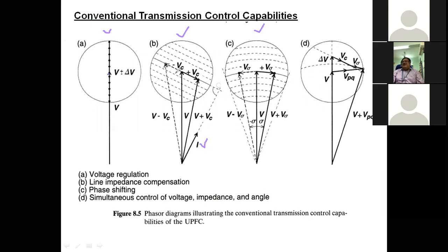In all normal loading or normal transmission lines, you never get a receiving end voltage greater than the sending end voltage. That's why we never use this type of series inductive compensation. We use series capacitive compensation, so that you get this, that is, voltage lags the current.